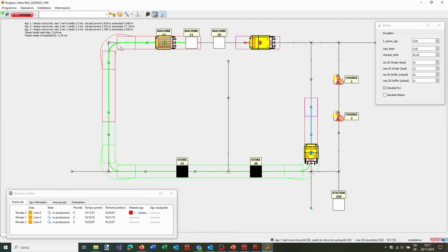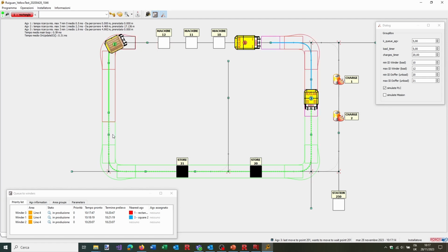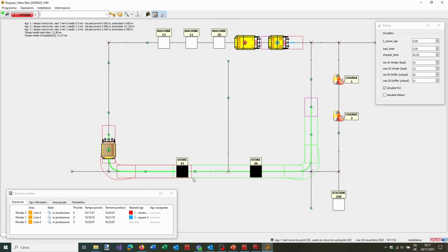In this way, while the AGVs will stop, they will stop either here, you see right now the green AGV has reserved until this point, and then later maybe it will reserve either until here or all the curve until the next point. Now we will see. Now it's coming down, now it's okay, it's not reserving. Okay, now it did. So, in this case it just reserved all this path. And so this means the AGV should never be allowed to stop on the cross.